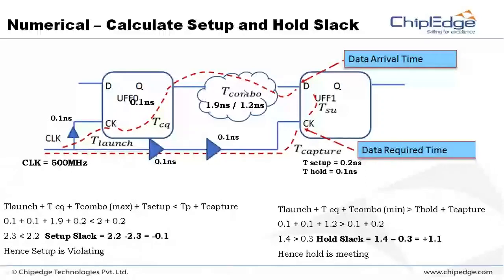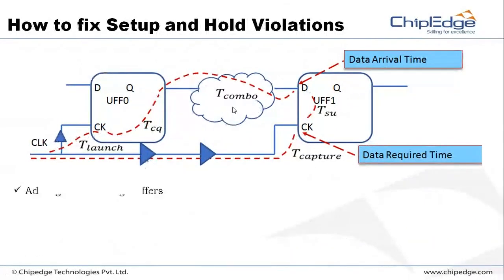Or if I have some circuit in the combinational circuit, some high threshold voltage gates, as I discussed in the beginning, high threshold voltage gates means they'll take more time. Let me replace them with the low threshold voltage gates. Then also the time will reduce, right? Like that, we will work out and reduce it.